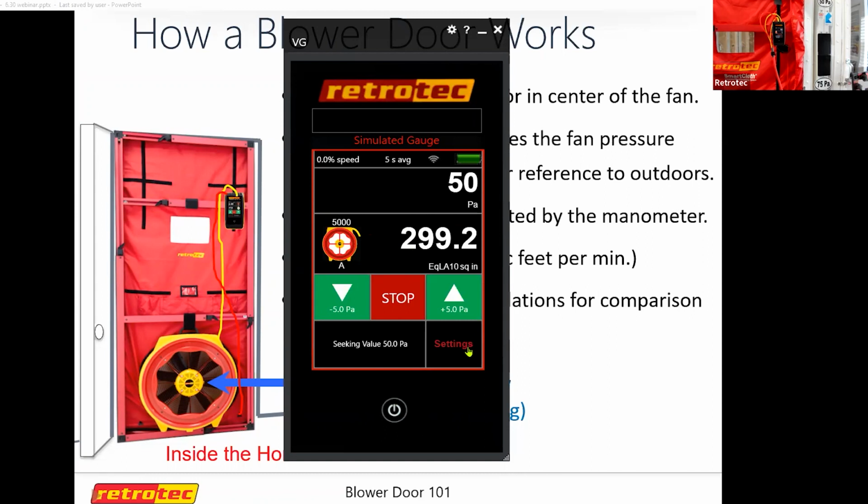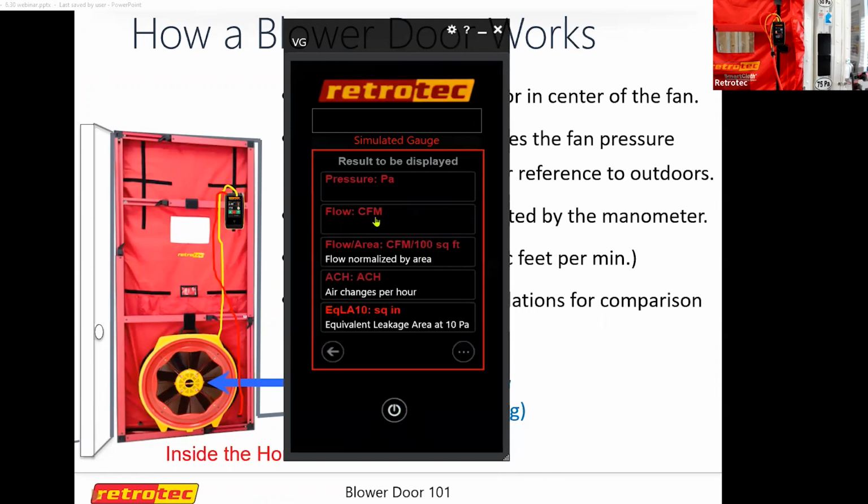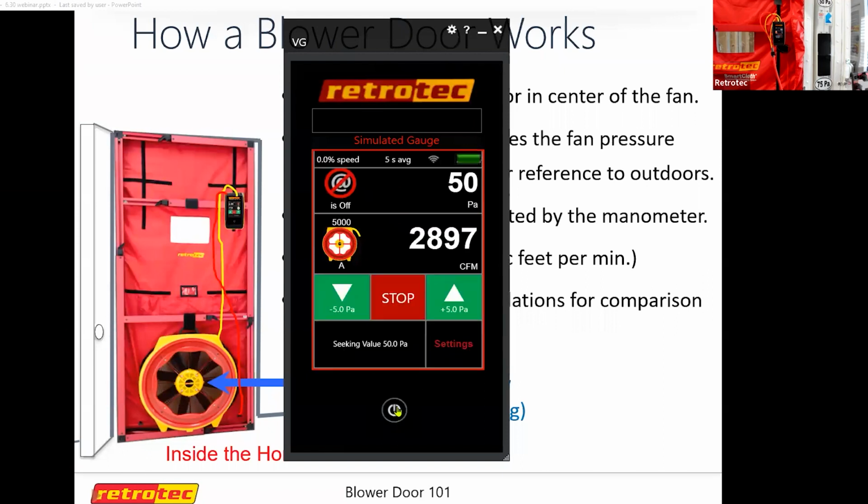So that's not really required by any codes or standards. Usually this is used just to show, if you get that number, you can actually draw the hole size out and show the homeowner, "Hey, with everything added up, this is the size hole we're looking for." That's usually what it's used for, just to give a visual aspect of how leaky that house is if you wanted to do that. But yeah, CFM50 is usually our basic way of reporting air leakage here.